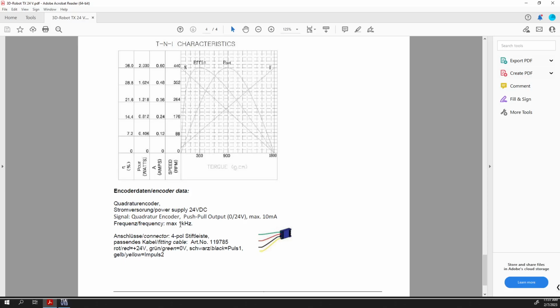So for example, let's say you've got bottles running down the line. You're trying to count how many bottles you've produced. Well, if you've got them on a high-speed machine that's just cruising by, you can't count them all fast enough. So we actually have dedicated hardware for counting them. Now, in this instance, with the S7-1200s, it is built into the PLC itself, which is nice.